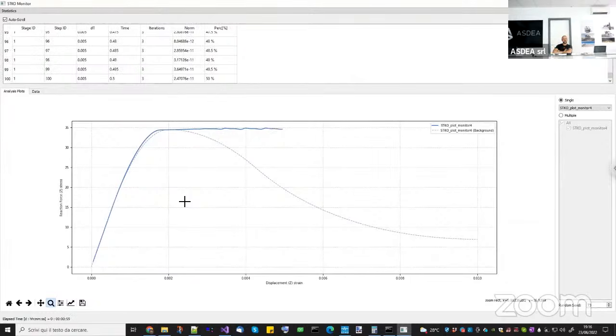So I performed the concept of fracture energy regularization, but this kind of problem is similar to the first one. It is a constant state of stress, more or less. It's not like the Truss, but it's pretty much like a constant state of stress. So it's very difficult for my model to understand which element should fail, because my entire concrete cylinder, except from the Poisson effect, is going under the same state of stress.